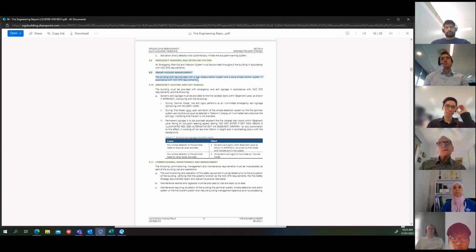So for instance, there might be a project that is more than 25 metres high, and don't quote me on this, but they might say, look, on this particular project, because we've got all these other safety features such as sprinklers, smoke alarms, early detection system, VESDA systems, lots of safeties, they might say, in this particular project, we've done the modelling and we don't think it's necessary to have a smoke hazard management system.